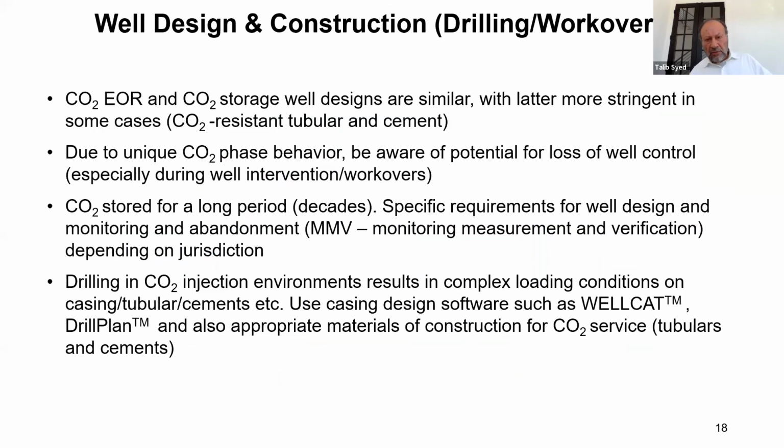Well design and construction for EOR and CO2 storage are similar, but CO2 storage may be more stringent, especially as we talked about CO2 resistant tubulars and metallurgy. Due to unique CO2 phase behavior, be aware of potential loss of well control.